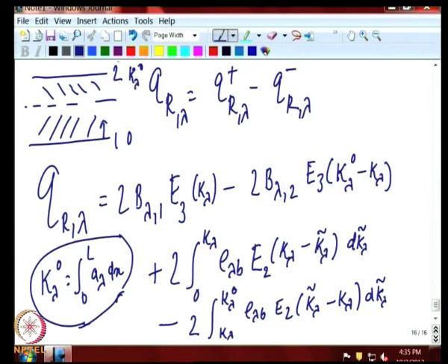So, when you come to this point, your travel distance is kappa lambda 0 minus kappa lambda, that is attenuation. So, that is the downward flux from the top surface. Then these are emission by the gas elements between 0 and kappa lambda, which reach the surface, and finally, emission from all gas elements above this.